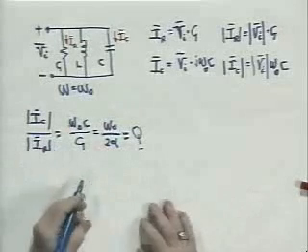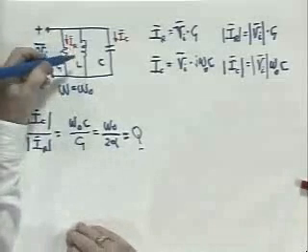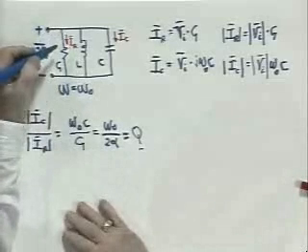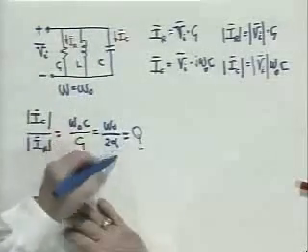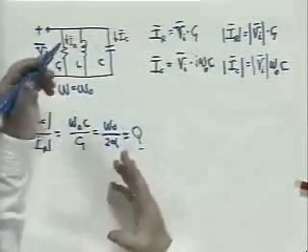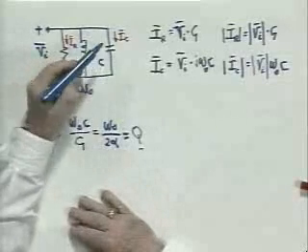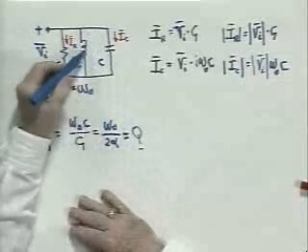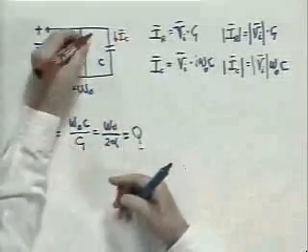So what this says is that if there's some current flowing in the resistor, say, to be simple, an ampere, and if the Q of this circuit, omega naught over 2 alpha, is 40, there's 40 amperes flowing in the capacitor, and exactly the opposite 40 amperes flowing in the inductor.